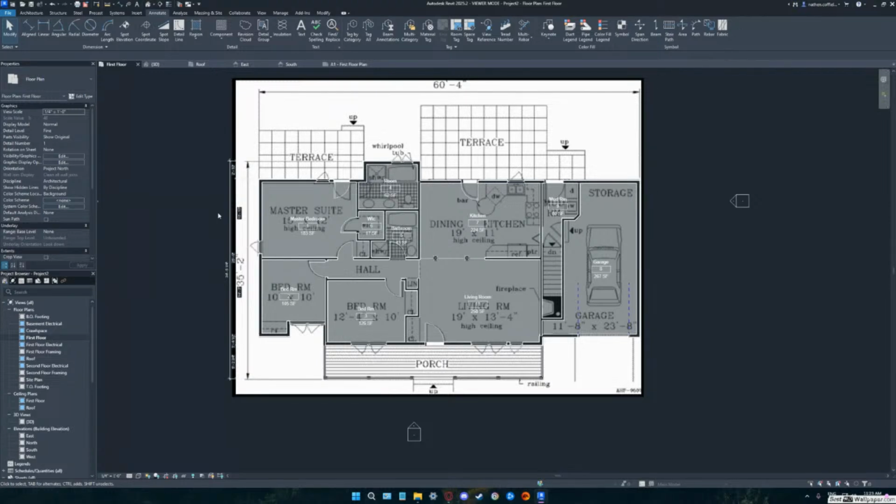Because then when you pick the wall, it's not going to highlight the dimension and allow you to move the wall from the dimension. It's going to be wanting you to pick the stove. And then if you change the dimension, then it's going to push the stove into the wall. Does that make sense? Yeah. A little bit? Yeah. I mean, honestly, to me, it would make sense more to do your dimensions once you have the actual structure built and forget about all the interior for now.